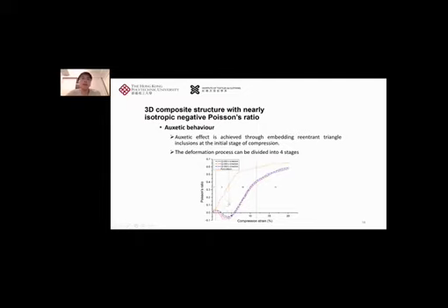But for the composite, the deformation process can be divided into 4 stages. In the first stage, the Poisson's ratio increases a little bit, because during this stage the inclusions inside the composite do not deform, but the silicon deforms to expand, and the inclusions don't deform inward to create the lateral contraction of the composite.